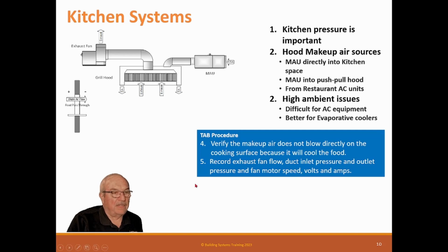One time I had a problem when I had a kitchen. It was a restaurant. And unbeknownst to me, it had a push-pull hood. The filter was incorrectly installed in the unit. I was the mechanical contractor. And it had about an inch open above the filter. We had to safe it off. But at the time, when the restaurant opened, we didn't have that safed.